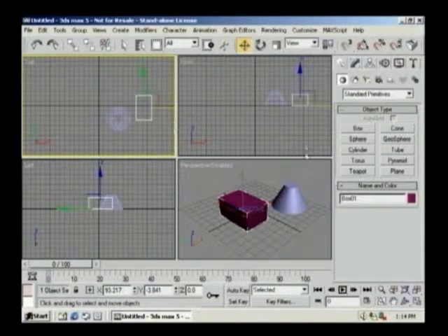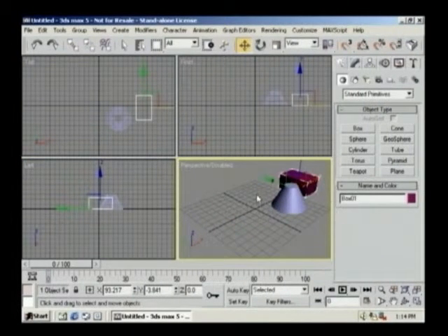But when I right-click in the Perspective viewport to make it current again, it will update with any changes that I made in other viewports, such as the top viewport. So it speeds up your redraw of the current viewport you're working in because it doesn't have to redraw what's in the disabled viewport until you activate it. Then it would update it. Now the hotkey to toggle an active viewport to be a disabled or not disabled is your letter D on the keyboard.